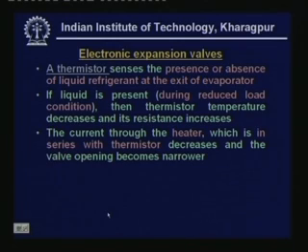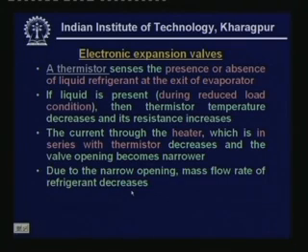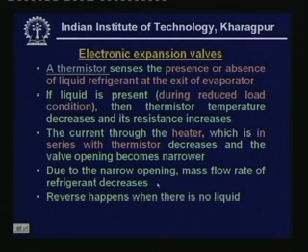So, as I said, the current through the heater which is in series with thermistor decreases when the load decreases and the valve opening becomes narrower. I am sorry, when the load decreases, the valve becomes narrower, and due to the narrow opening, mass flow rate of refrigerant decreases. Okay, and the reverse happens when there is no liquid.